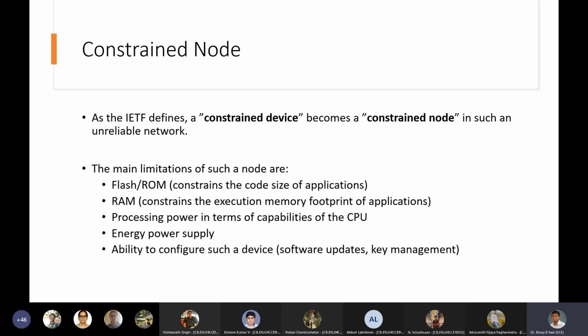Unfortunately, if you have a smaller RAM, you cannot store a large amount of data in the buffer. It's basically like a buffer that you have. For example, if you want to store 100 values before you start processing, some of the microcontroller boards may not allow you to do that. Some other boards which have a larger RAM will allow you to store 200, 300 values in your RAM before you can do the processing.